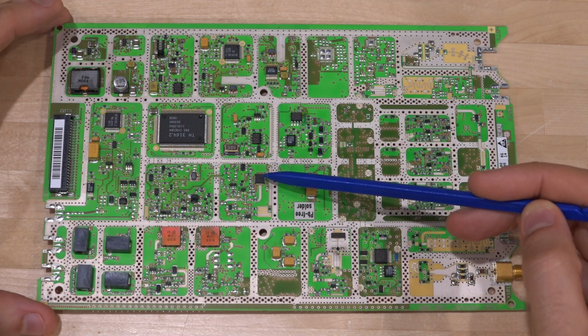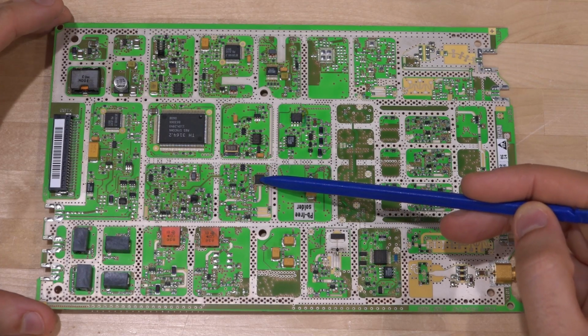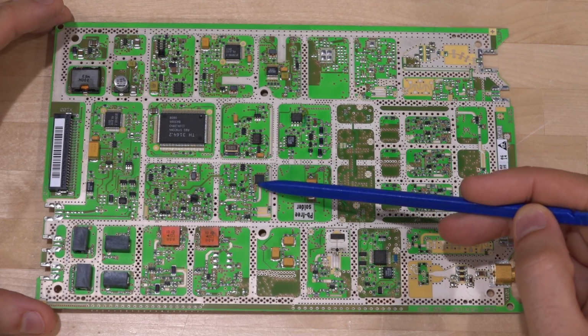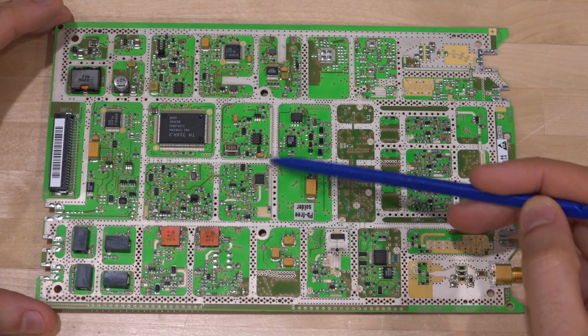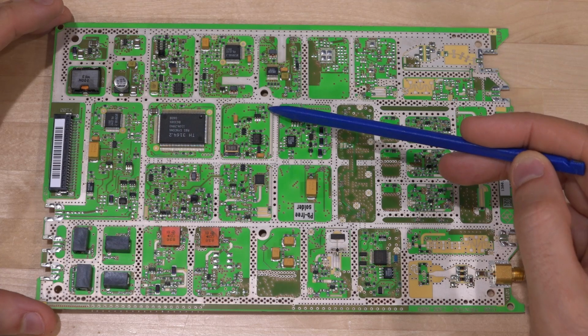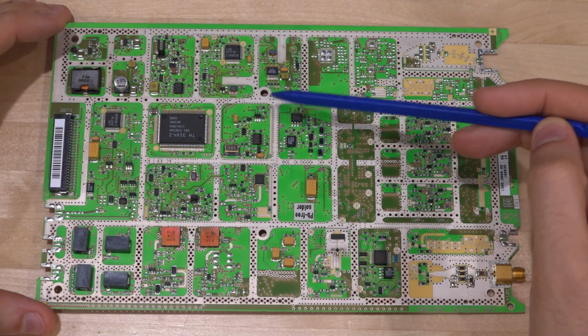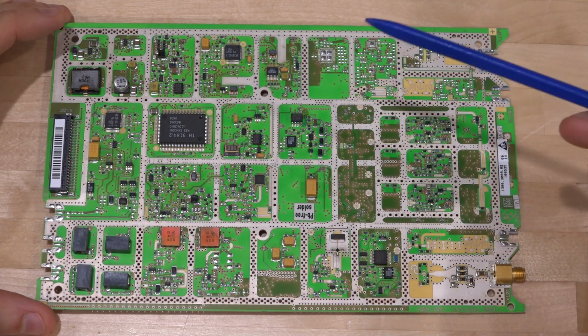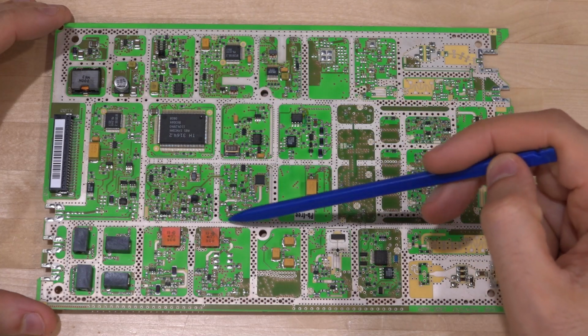I'm going to have to look at the part number. This looks like a Hittite part or an Analog Devices part. It would kind of make sense because we have this output coming over here, then it splits into multiple directions. And one of them seems to be coming back over here and fed over to these regions. So I would say the PLL core is probably here.